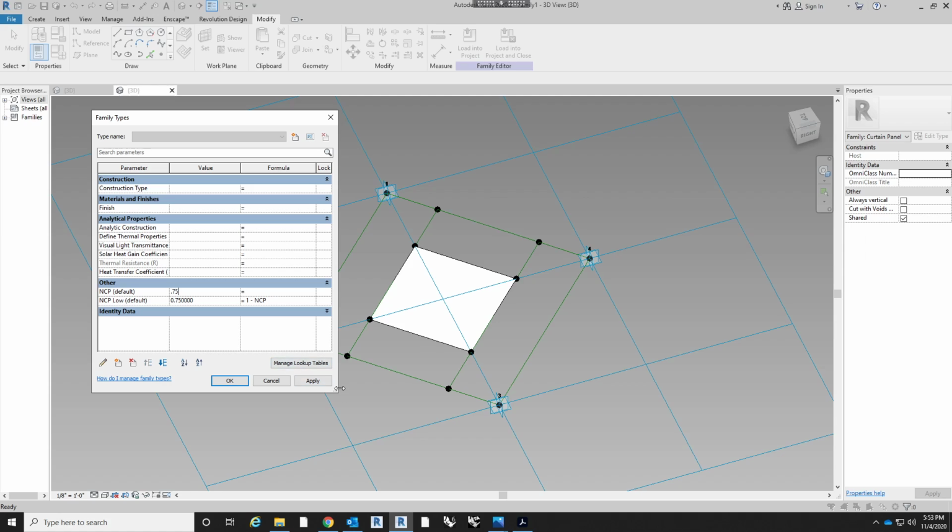This is important to note when we are influencing our parameters through Dynamo. We need to know that 0.5 is basically at its smallest. It doesn't exist, and it's going to error out if we do it because there's multiple points in the same position. And we also need to know that it doesn't matter if we're below 0.5 or above 0.5, but that's the range of values that we'll have to influence if we want a nice true gradient from one side to the other.